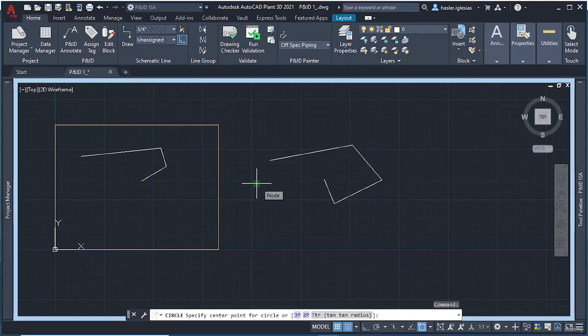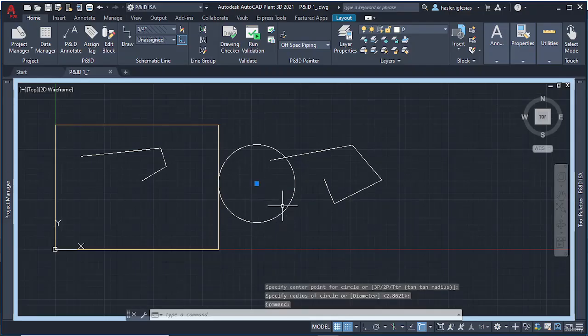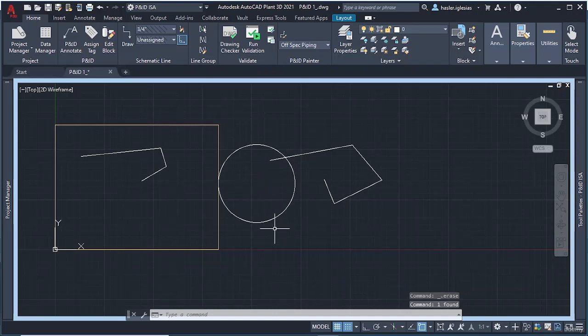And look, there appears a green circle with an X that is exactly on the point I just drew. And it will allow me to center my circle there. And then I can just select the point and delete it. And I will have this circle centered exactly on that point. Okay, so that's the command PO, or point.